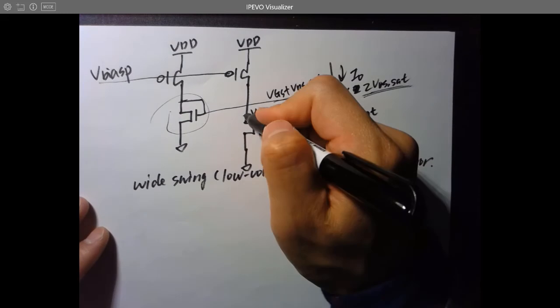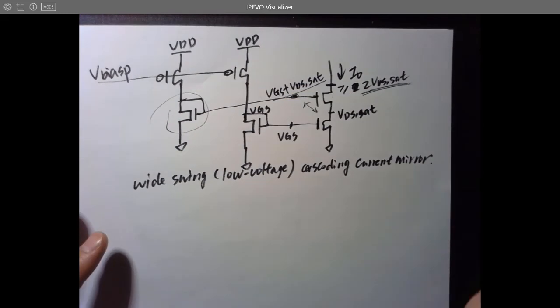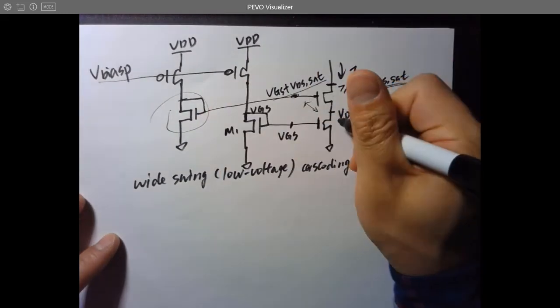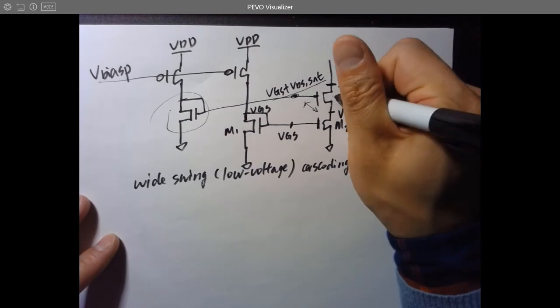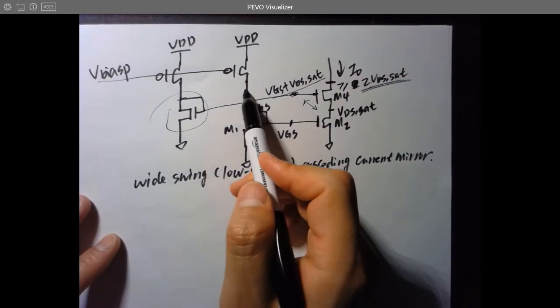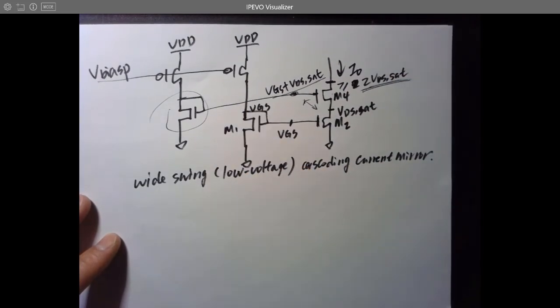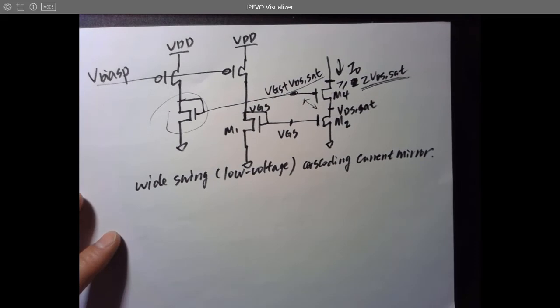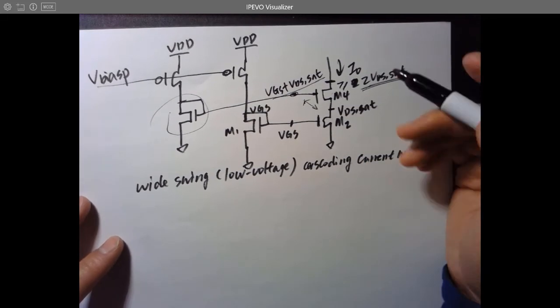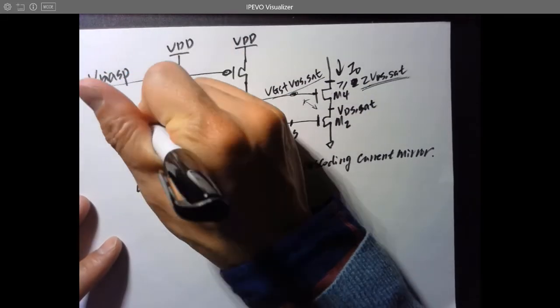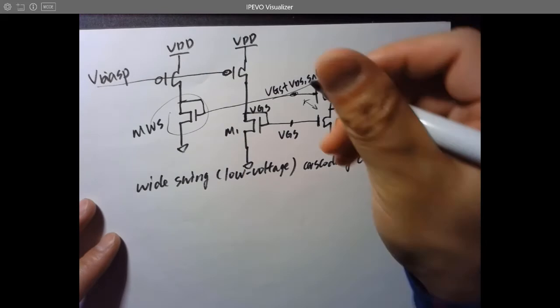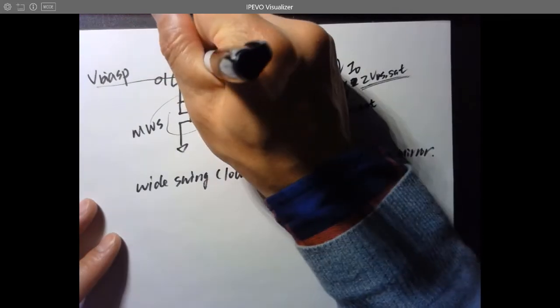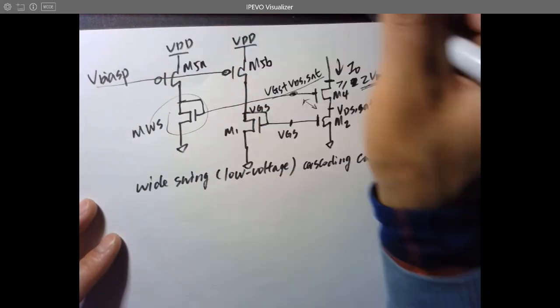And we are going to run through this in LTspice as well. Now let's label these transistors. This is M1, M2, and we call this M4 because in the future there's another one to be added over here, so we just want to keep all these names of the transistors consistent. And this is called a wide swing. And this is M5A, M5B.